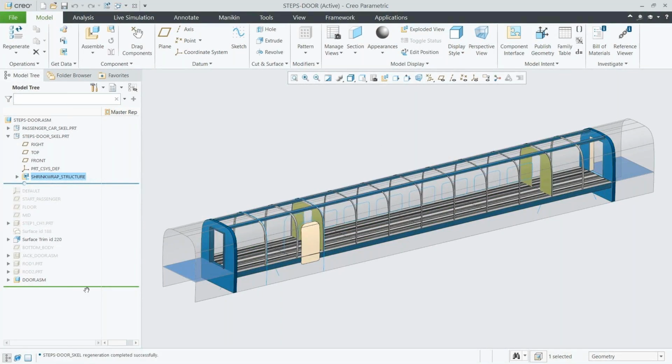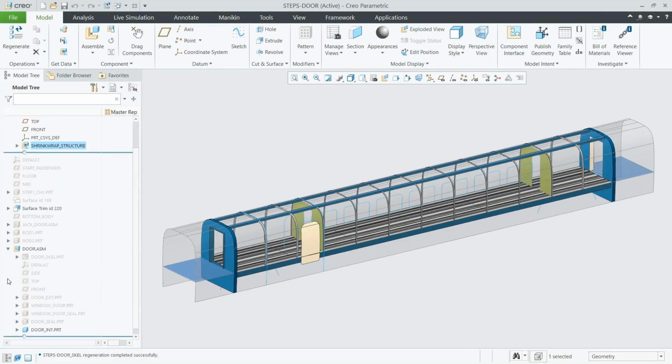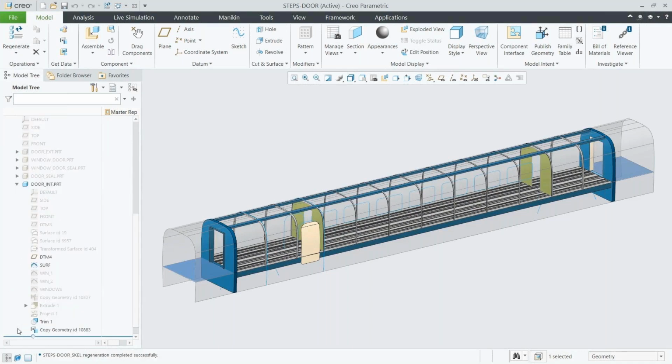You can see here you have that structural arch patterned out. You have the shape of the windows there. You have the shape of the exterior. The shrink wrap, if you're not familiar, wraps up your surface geometry, or rather wraps up what you see, and strips a lot of the data behind it, so you can have this whole assembly open and be able to see where the floor is, where the top is. You can even reference those models, but you don't have to have all the weight of all that CAD data behind it, so you can effectively work in large assemblies.